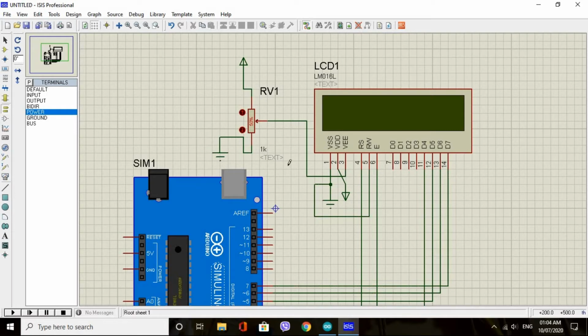The 4 wires: 2 are for power supply, and the other 2 are for data in, data out, like this. So that is also easy. In that case, you don't need to include this variable resistor, because in that I2C bus IC, behind it, there is also a variable resistor like this to increase the contrast. So our circuit is complete.